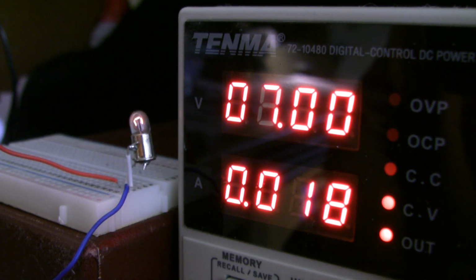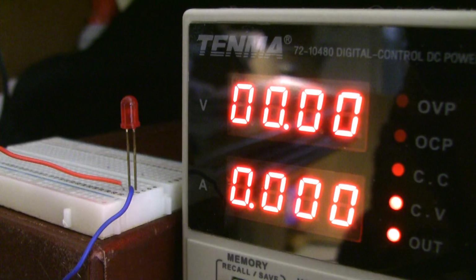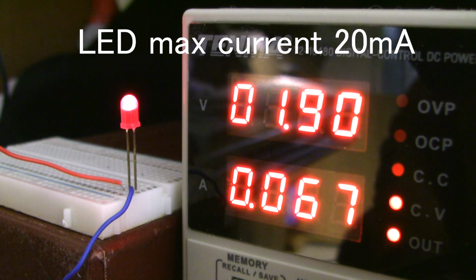What happens if you slowly increase the voltage to a bulb? We see that the current slowly increases with the voltage until the bulb is lit. Now what happens if we do the same with an LED? Nothing happens at first, no current flows. Then at a certain voltage the current increases very fast and goes way over the LED's maximum current.